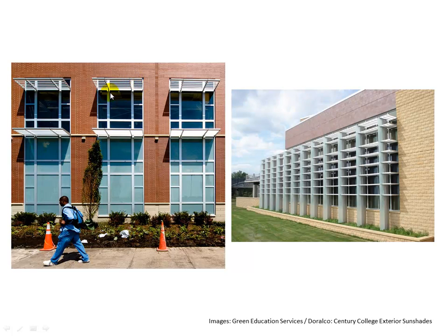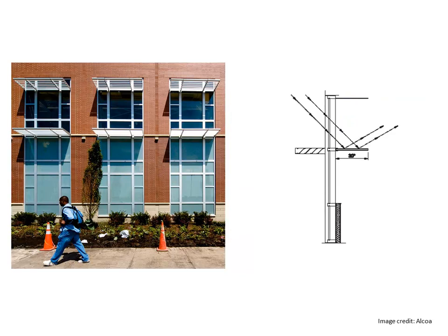Some of them depend upon the side of the building. If you have a corner of a building that's oriented, let's say, as a southeast corner, you might need shading devices that are both vertical and horizontal. You guys will learn more about this later, but there's actually an exterior shading device and an interior light shelf in this design.